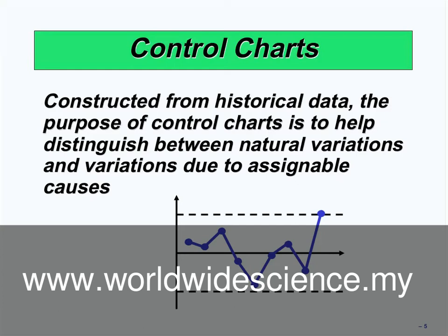For example, if the machine is producing 500 parts in 1 hour, in each hour the quality manager or the operation manager can choose 50 out of these 500 parts and take these 50 parts to a laboratory and test all of them. The sampling shows whether all of the products are in control or not. So the most important thing is that the operation manager can choose the sampling and take it to the laboratory and test all of it.